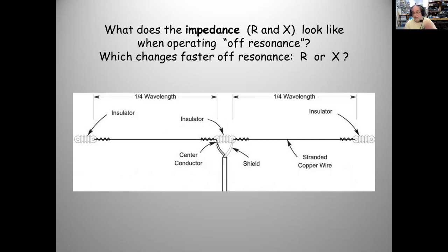Well, my NanoVNA does measure it. Oh, okay. What is impedance? Well, it's a combination of the R and the X, isn't it? So what if my antenna ends up pretty close to 50 ohms, and my coax is 50 ohms, and my radio wants to see 50 ohms. Then I'm really happy. Everything looks like it's tuned up. It's in resonance.